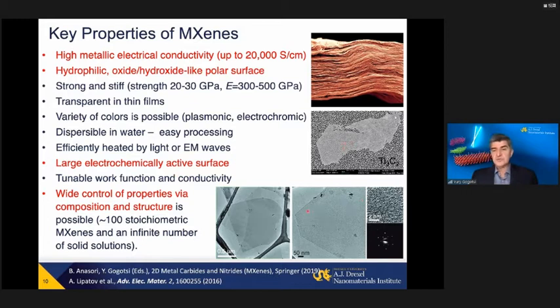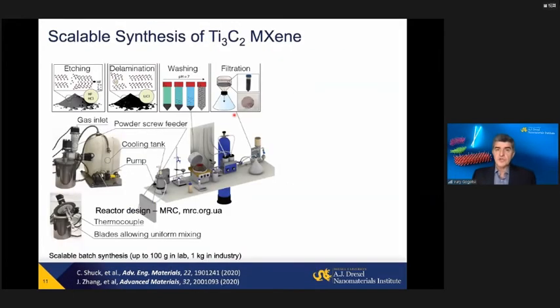Otherwise, these flakes look like flakes of many other 2D materials. You see, for example, a hexagonal imprint of the structure. Those are single crystals. This is a single layer, single crystal titanium carbide, Ti3C2. This flake is about 20 micrometers in length. And you can pack thousands of those flakes in this type of structure, similar to, say, graphene or graphene oxide paper. And it's all possible.